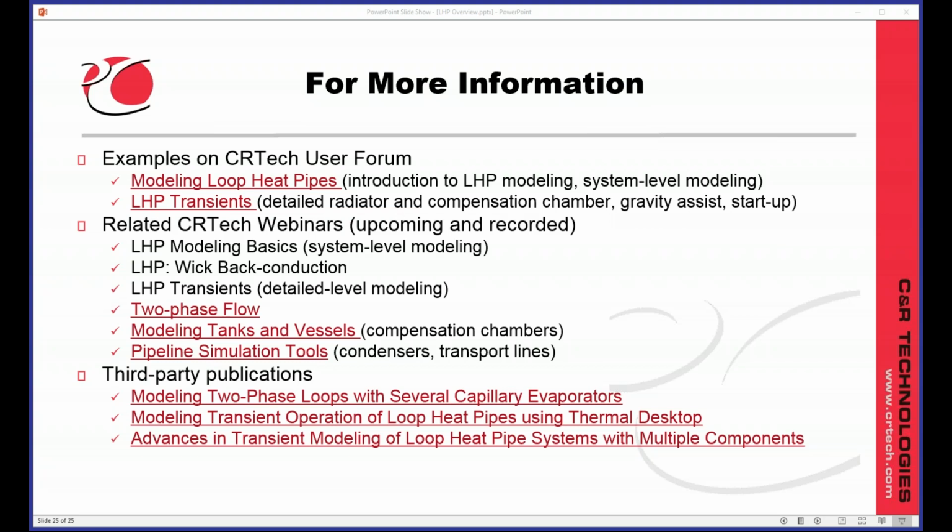I wasn't talking a lot of modeling today, but I don't think I deal with that question in later classes. So one partial solution is there's a thing called a wick interface, which helps you model the flexibility of a primed wick. That's more for fast time scale events. It's also possible to have kind of leakage paths. So if you want to model partial deprime, like during a startup event, you had a high stress period and you want to let vapor kind of sneak through onto the wrong side of the wick, you can do that. But otherwise, I think the most honest answer is no.